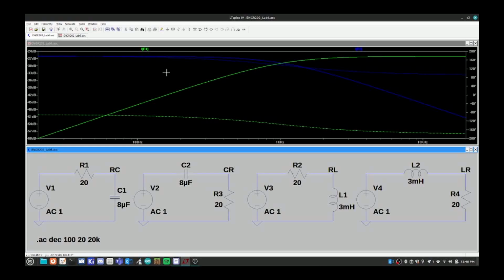But remember that the current is not going to be the same magnitude as the voltage across the resistor. It has the same frequency response, and I think if you did the math to convert, for example, from this 20 ohm resistor, and you've got some current at like negative 30 dB, you would probably get the right voltage that you want. Anyway, this is the right frequency response, and if you remember that the voltage will be a factor of 20 times higher than the current, this works out.